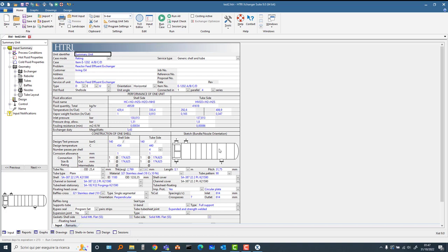Let's say other characteristics. If we look at the quality, the quality is the percentage of the vapor weight fraction. On the hot shell side fluid we have 1, so 100% vapor at inlet, and 0.9 and something at outlet. That means that there is a condensation of a very small fraction, less than 10%, but there is a condensation.